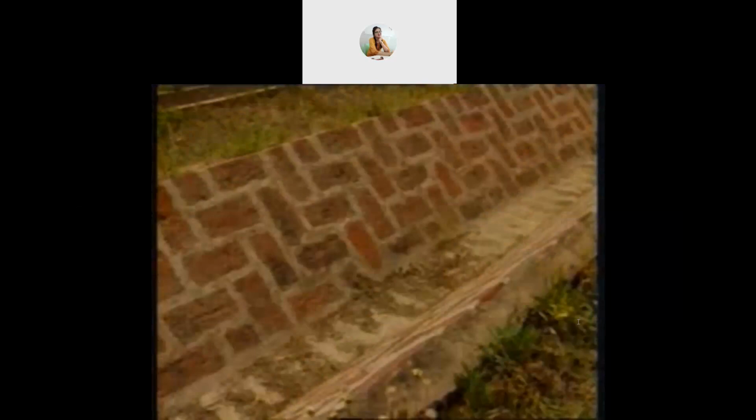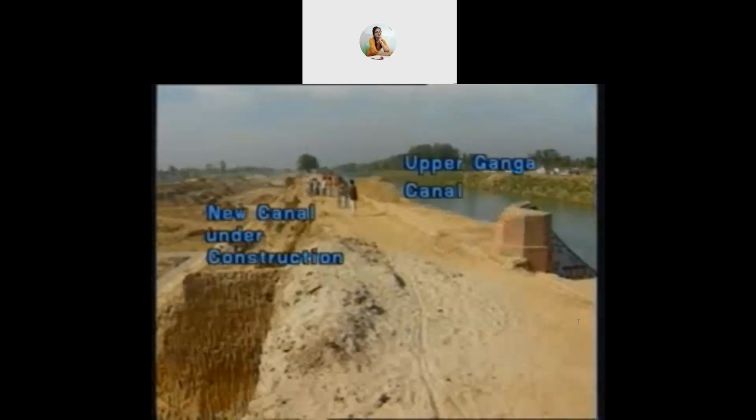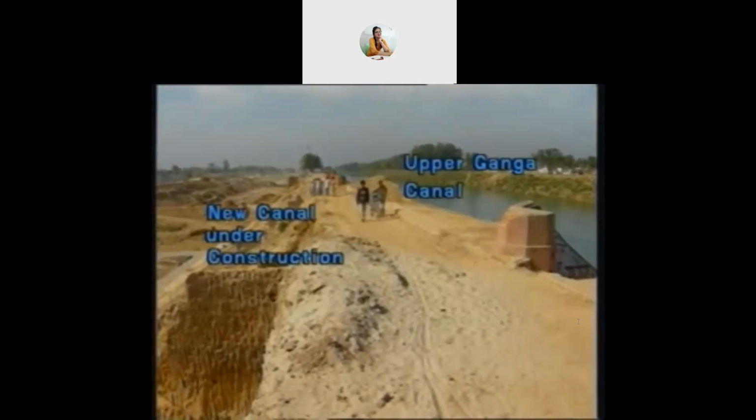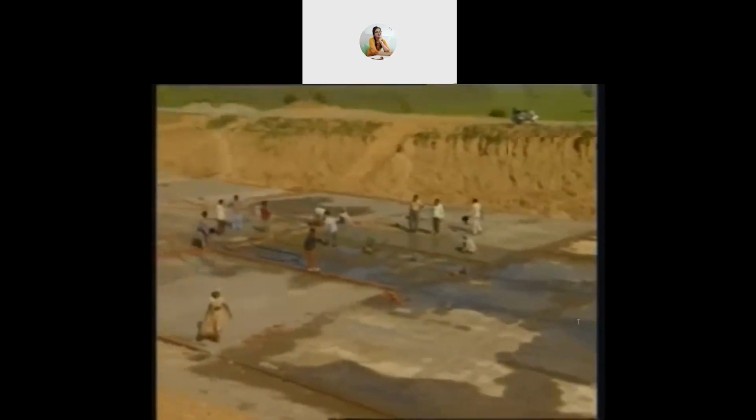Out of so many types of linings, what are the criteria used in the selection of a lining? We put this question, with reference to the modernization of the Upper Ganga Canal, to Shri R.C. Goel, Chief Engineer, Irrigation Department. The basic criteria are two: cost and the time that we use in their construction. As I said, concrete lining is definitely faster to do when using bed. And cost-wise, concrete lining in the bed is a little cheaper also.